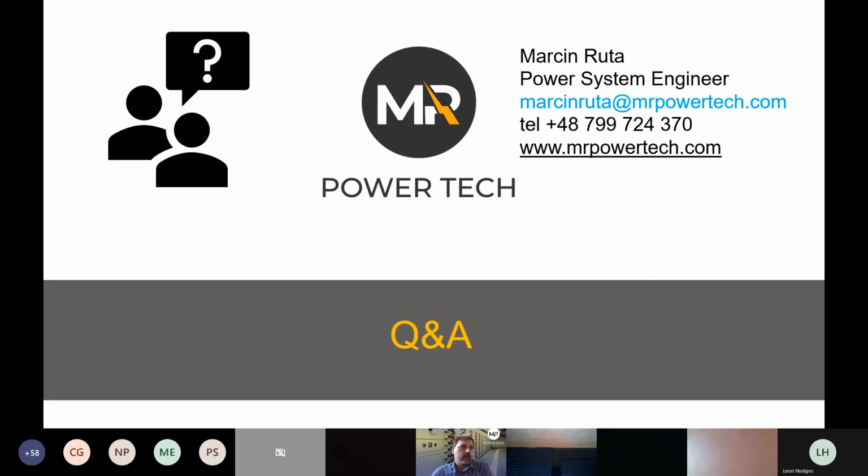In case you see that something is happening, a pending failure, as we call it, you don't send people to work. So you reduce the risk, or you actually avoid the risk. But it will not have any influence on the calculation, unfortunately. Generally, the arc flash risk assessment is for calculating the energy of an arc flash explosion, to build some precautions for how to build the mechanics of the switchgear and which clothes the maintenance people should use to be safe when working with the switchgear.